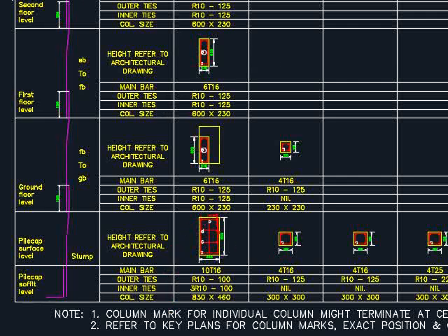Outer ties represent the shear stirrup, and the inner ties tie the reinforcement bars, especially the intermediate reinforcement bars in the columns. Normally, the inner ties are required when you have more than 4 reinforcement bars in the column, where these bars are not placed at the corners of the columns. And there will be the main reinforcement bar as indicated in the drawings.